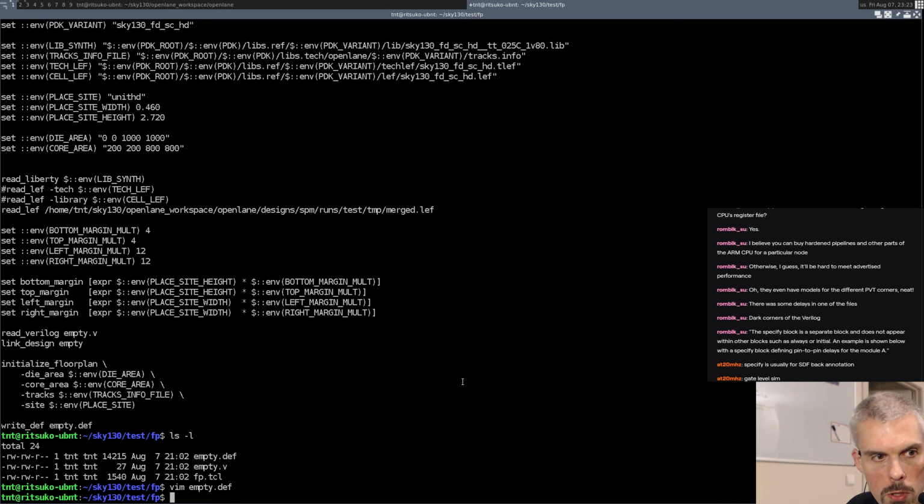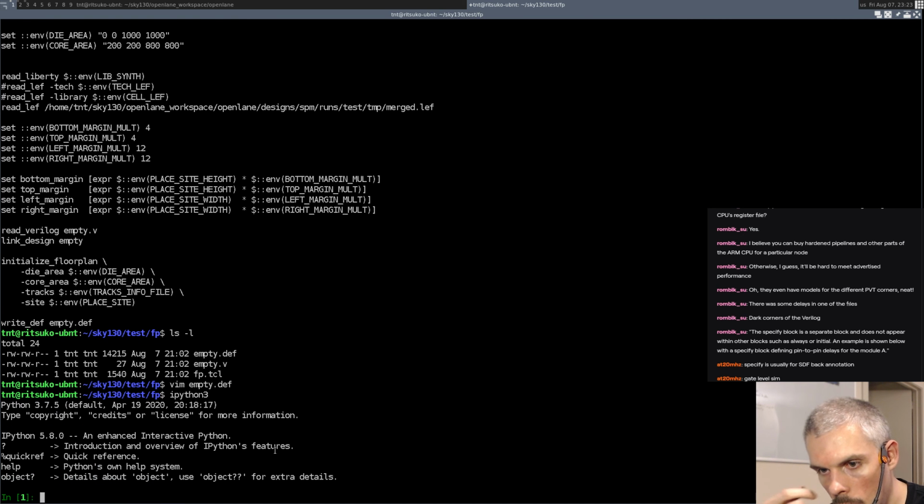But what I wanted to show is called OpenDB, and that's a way to manipulate designs and the DEF and the LEF files. And OpenLane comes with Python bindings for that. So if I start IPython, let me take my notes. Okay, so import opendb Python as odb.